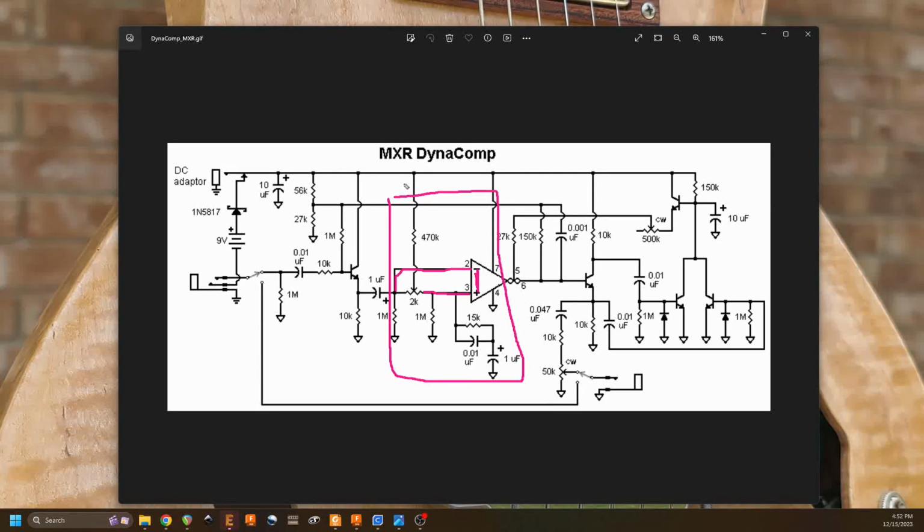And so this bias voltage that is coming down here into this pot allows us to make very small adjustments to the bias on these two pins. Now, with ideal devices, this trimmer potentiometer here would be set exactly in the middle, and you'd have exactly 1K from our bias to the negative terminal and 1K from our bias to the positive terminal. However, that's not always the case. Sometimes you have slightly imperfect devices, and so this trimmer is just to allow you to make small adjustments there to really dial it in.